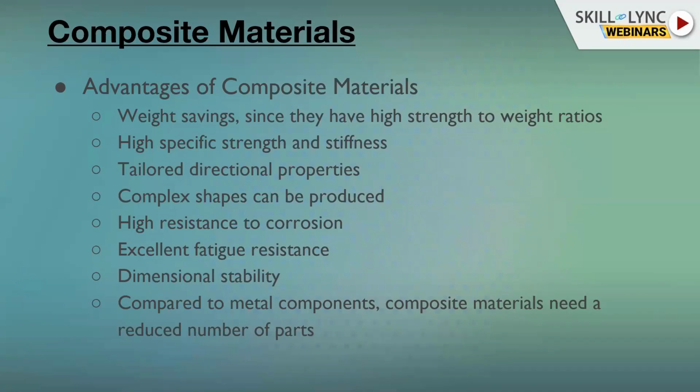What I mean by that is, when the parts are built or designed, they are designed in such a way that, considering the amount of strength required in each direction and the load cases, the material is added in particular directions to overcome the loads that are being applied to it. So we don't need strength in all directions. What we need is specific strength in specific directions to overcome the operational loads.